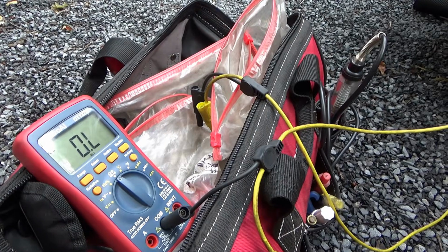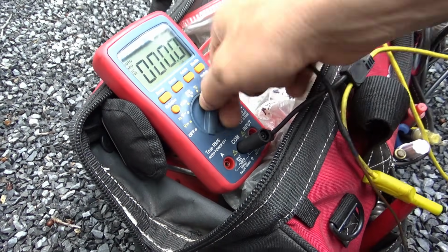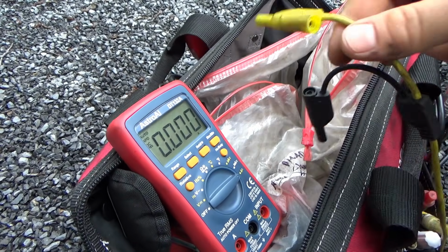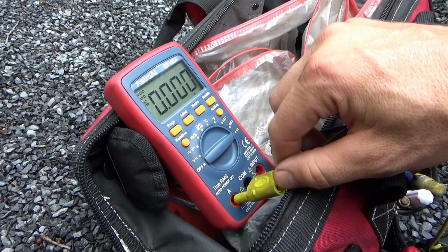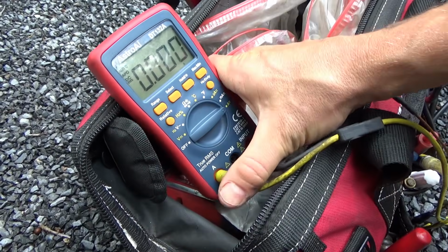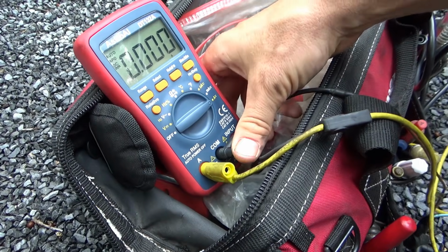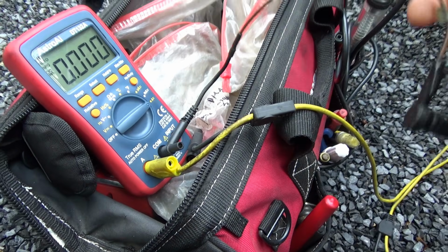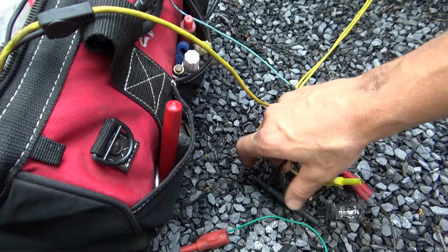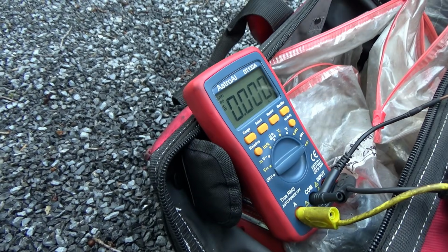You want to think about the current flow. We can even measure the amperage using the amp setting on the voltmeter. So current is going to be coming in on the control wire into here, and instead of going through the compressor, we want it to go through our baby test light. So now it's going to go through the test light, and the test light has to be grounded, obviously, and that will be this black lead right here going to body ground. Okay, so we have amps, we have the test light.